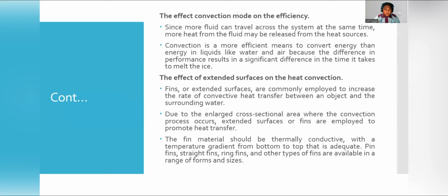Next, the effect of extended surface on heat convection. Fins or extended surfaces are commonly exploited to increase the rate of convective heat transfer between an object and the surrounding fluid. Due to the enlarged cross-sectional area where the convection process occurs, extended surfaces or fins are exploited to promote heat transfer.